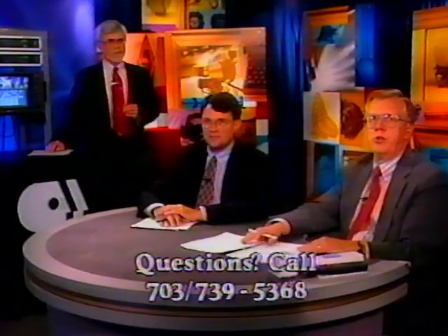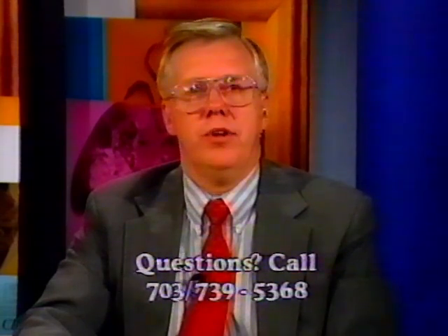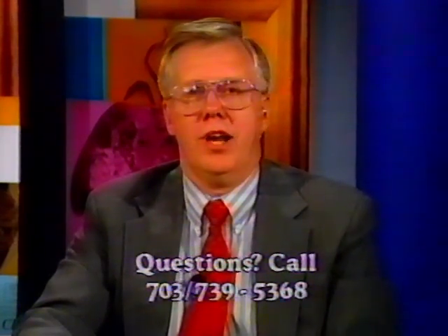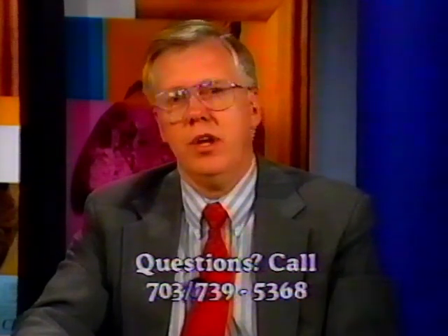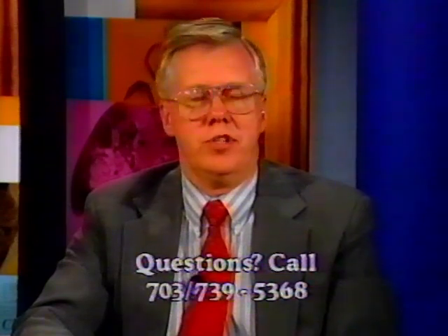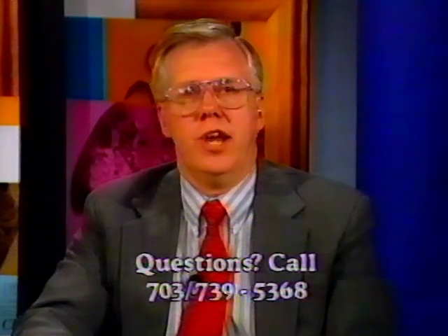Yeah, that manual tuning process is indeed what we were showing to you. The IRD has enough of a brain that it'll go out and find that feed if it has to, but it would far prefer it, and it'll make it a lot faster for you if you simply load the L-band frequency and the polarization and the data rate and the FEC, the combination that Andy discussed, and then it'll get there in 60 to 90 seconds.